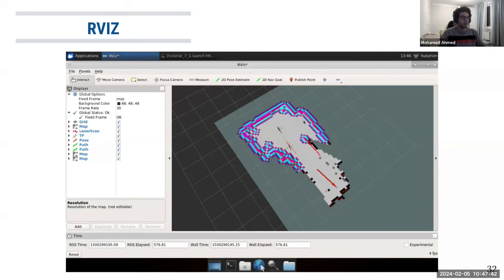Maybe one module is just drawing the map, this outline map. Another module is trying to see what the drivable area is, where we can go and where we can't go. This is typically an occupancy grid. So what is an occupancy grid? An occupancy grid is a map that we draw, a pixel map. It has a value from 0 to 100.